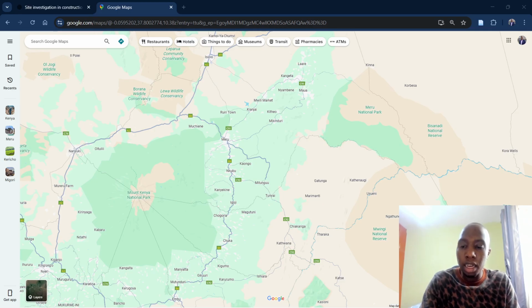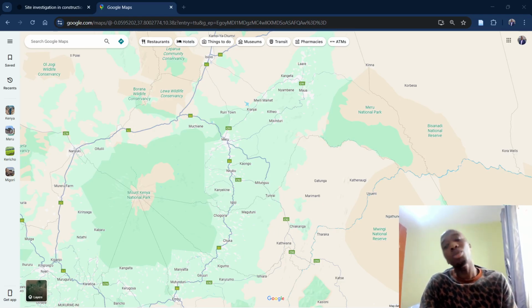Topsoil, maybe here is red soil, and so on. Here you have maybe bedrock. So how do you identify the depth of the bedrock? You need to identify that when you are doing soil exploration. Maybe I need to collect samples of the black cotton soil that is down here. So I need to dig a pit and extract samples from here.